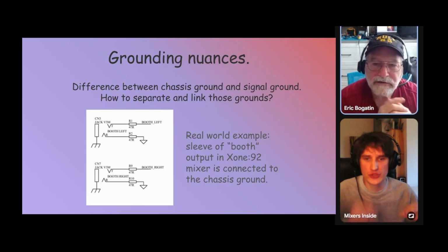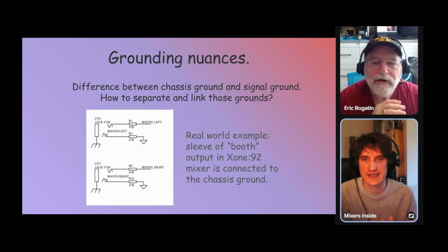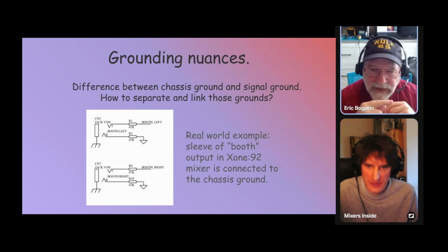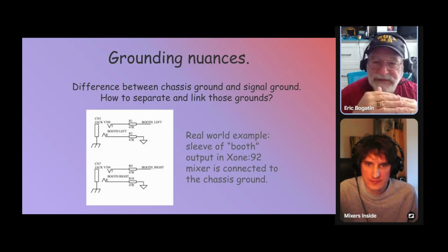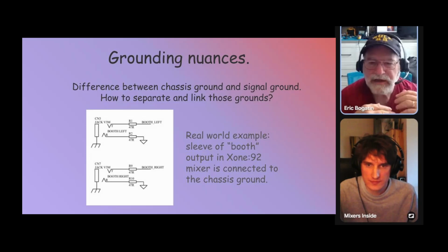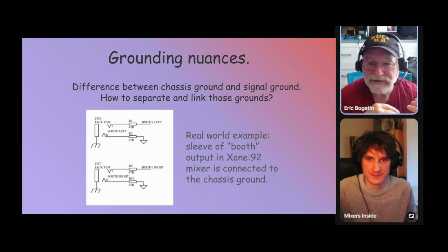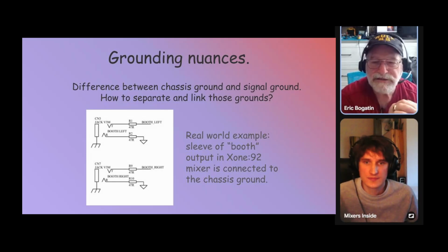Excuse me, but what do you mean by low side? Right. So in your example here, you have a signal, and you have its return. I call the signal the high side. That's where the higher voltage is. The low side, I hesitate calling it the ground side because we're going to change different grounds, but it's the coax, the shield of the coax.